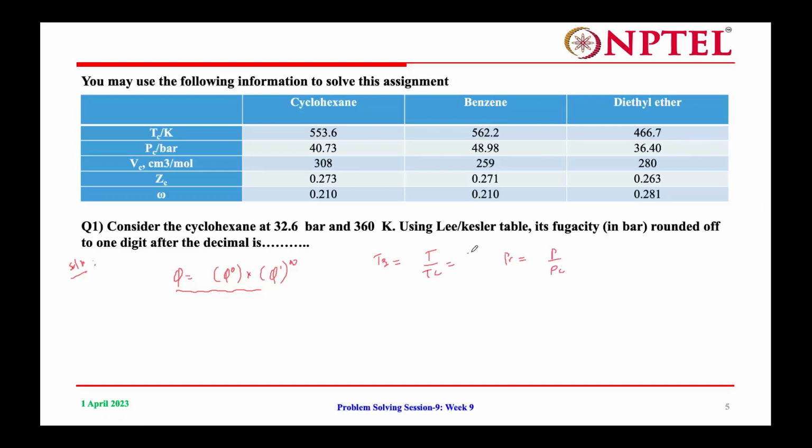Here T is 360 divided by T_c, given for cyclohexane as 553, so T_r is 0.65. P_r is 32.6 divided by P_c, 40.7, which is 0.8, right?